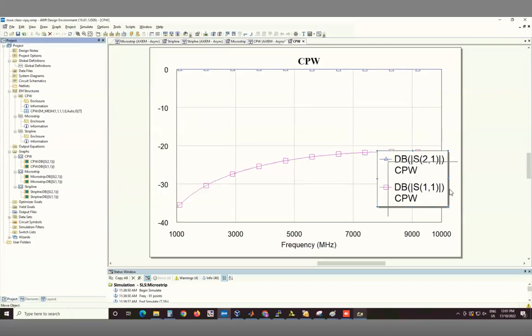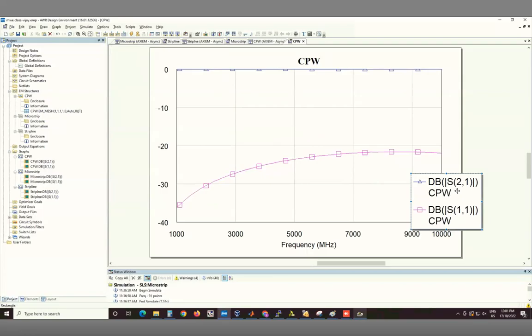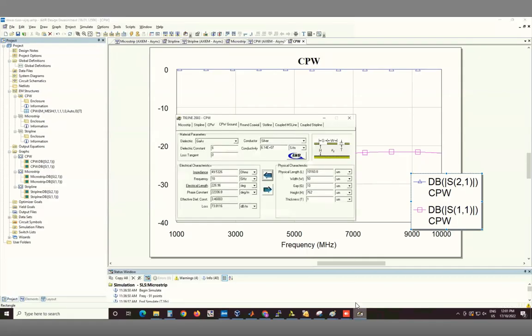So now you see there was hardly any difference because most of the capacitance is coming from the very small gap, and 762 microns is too far away for that ground plane to make a difference. And this one is a lot closer to what we calculated. Right? That is for 50 and 10, and that is 50, and this is pretty close to that, as opposed to the previous one where we had much larger gaps.